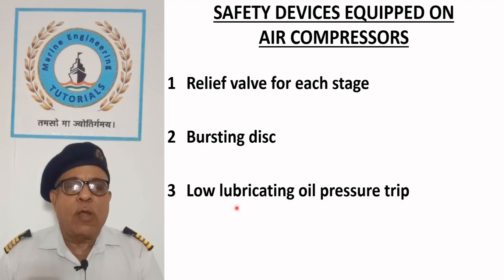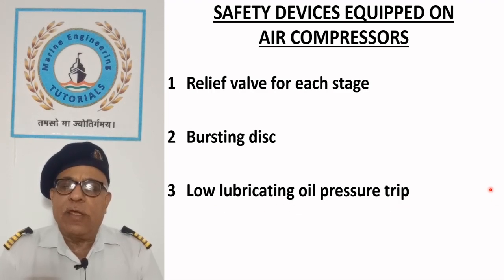Low lubricating oil pressure trip. For safeguarding the air compressor against loss of lubricating oil pressure, a low lubricating oil pressure trip is provided. It is a pressure switch which shuts down the compressor when lubricating oil pressure drops below the preset value.